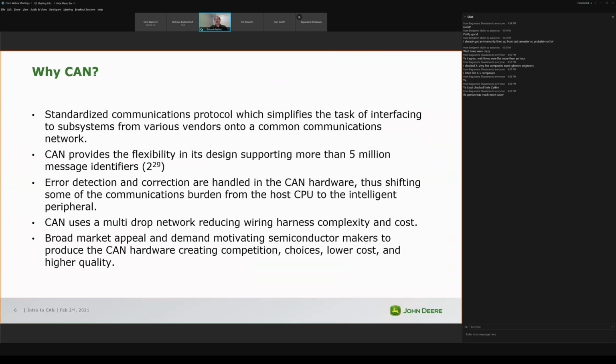And also it's multi-drop. Compared to RS-232, which is point-to-point, and RS-485, which maybe you are familiar with, 485 is multi-drop, but it isn't truly multi-drop because it cannot detect if someone else is talking and could stomp over them. CAN does give you that benefit.